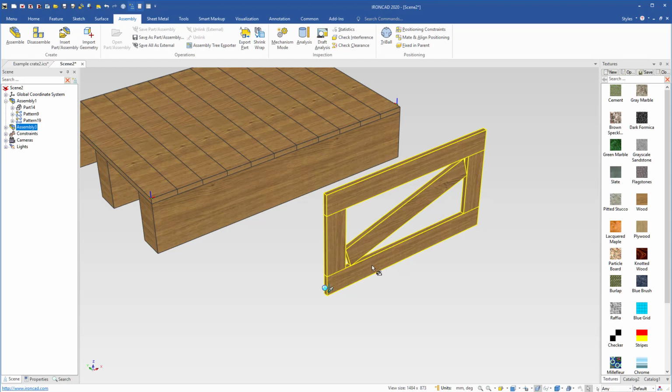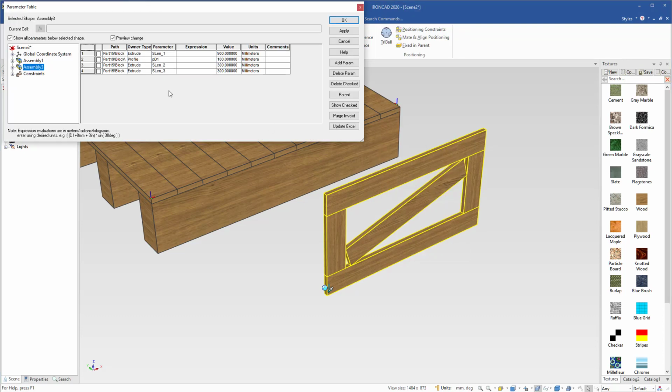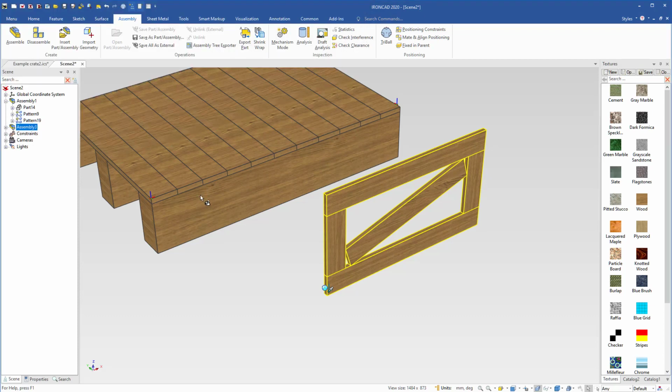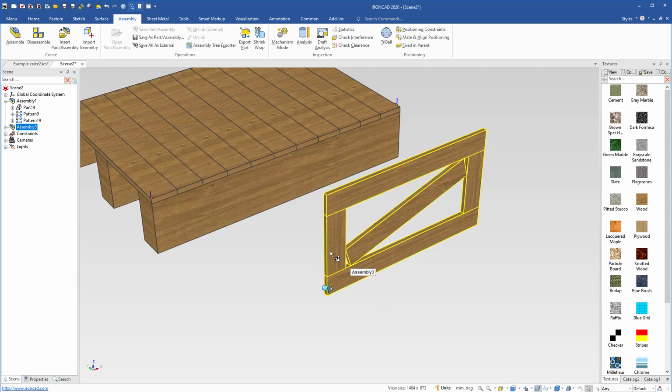One, we still need to build the parameters to this so that it will adjust from the assembly level. So we need to go to the assembly, go to the parameter table, and notice if we turn this off, there's nothing at the assembly yet. So we're just going to go ahead and drive this guy, and we really just need a length parameter, and we called that the side. If you remember, we called that, let's go ahead and go back here. We want to set a parameter that's called side length, SIDE, capital LEN.